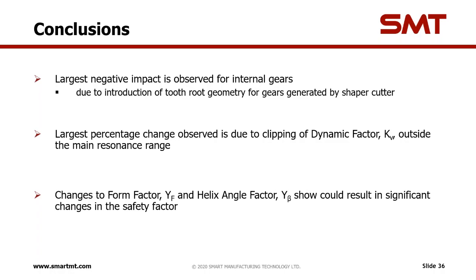The effect of them on the overall damage on the gearbox might not be. So we would need to actually take into account the amount of cycles which each load case corresponds to in that case. The general differences that we observe are in the bending safety factor, and this is both due to changes in form factor and a helix angle factor.